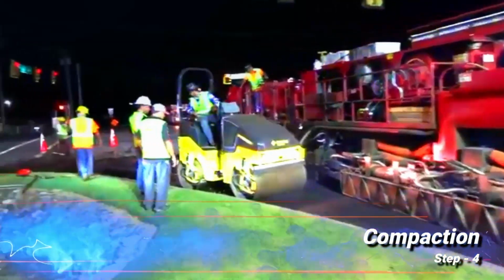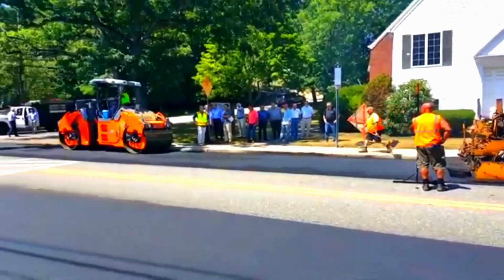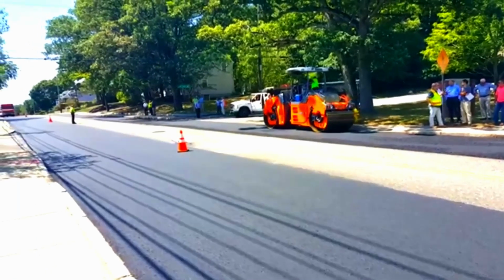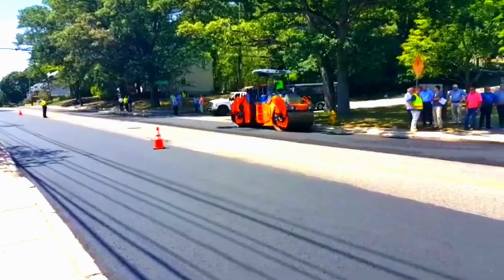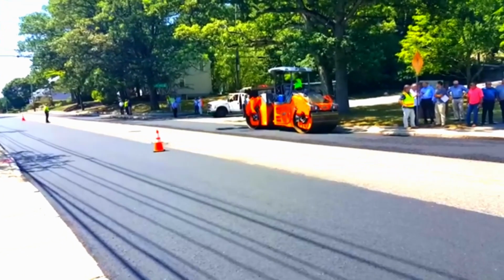Step 4. Compaction. Once the asphalt is laid, rollers compact the surface to increase density, strength, and durability. Proper compaction prevents air voids and moisture infiltration, reducing the risk of early pavement failures.